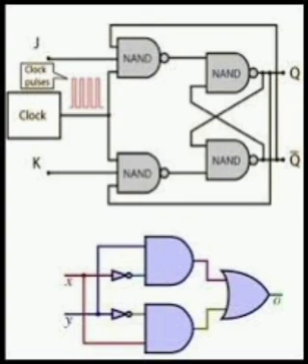It is a combinational circuit that converts binary information from n input lines to a maximum of 2 power n unique output lines. If the n-bit decoded information has unused or don't care combinations, the decoder output will have fewer than 2 power n outputs. Total number of output lines m is less than or equal to 2 power n, where n is the total number of input lines.